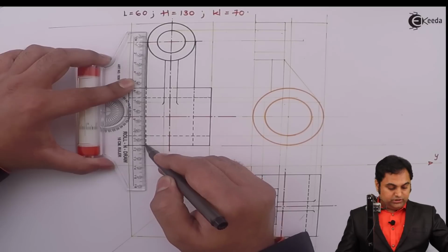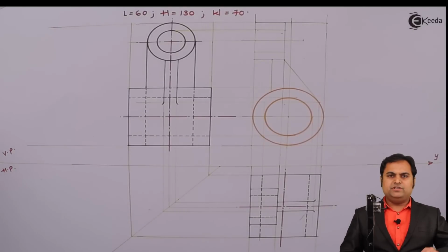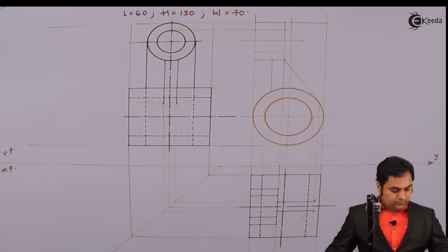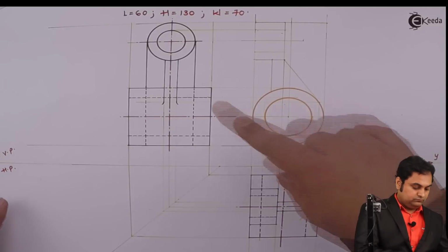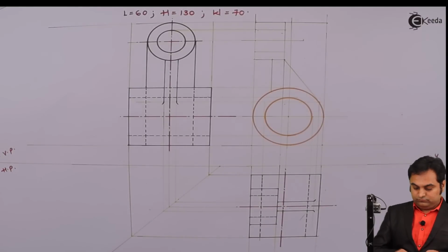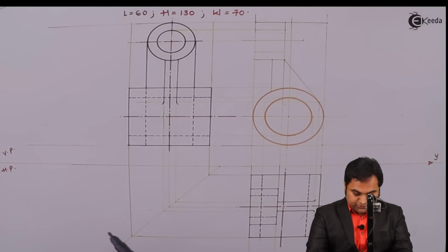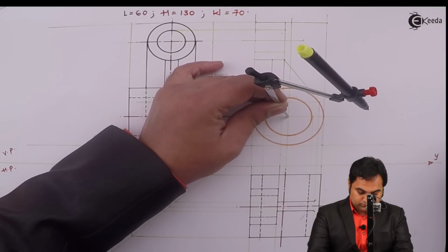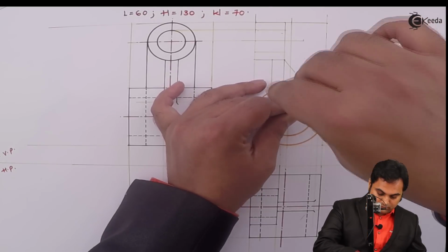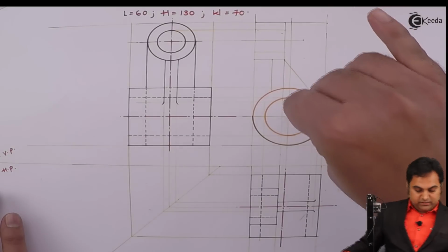Next, I'll be coming back to the front view, which I have to draw as the sectional front view. Now, once you have drawn the plain front view, the sequence is make the outline dark first and then look for the cut portion. So here I'll be making the outline dark. For that, this circle will remain dark where it is connecting the rib, that is up to this location. Up till here. Next, whatever the outlines are there, I am quickly making them dark.